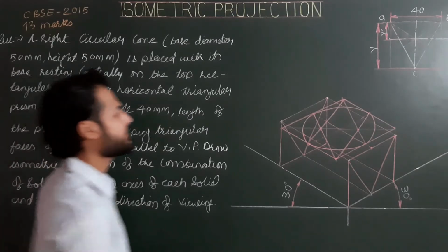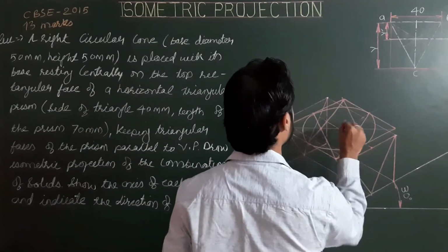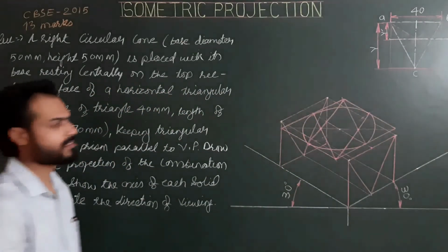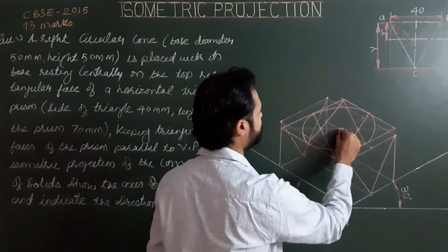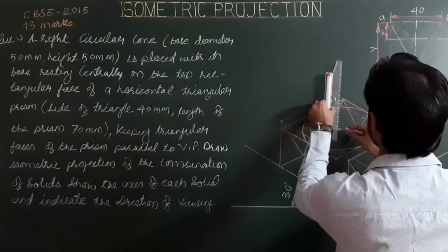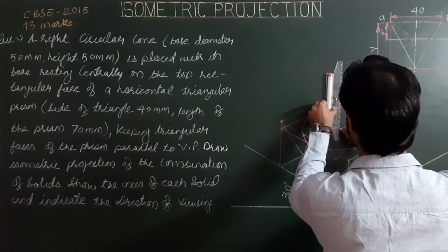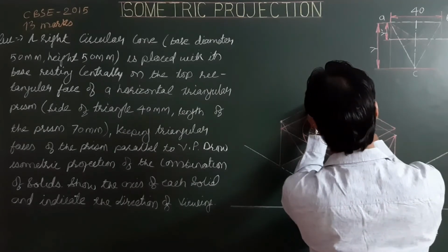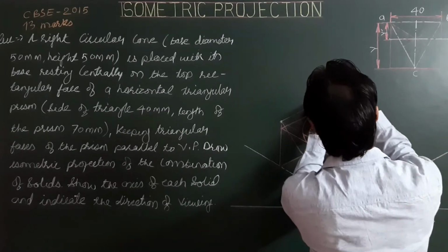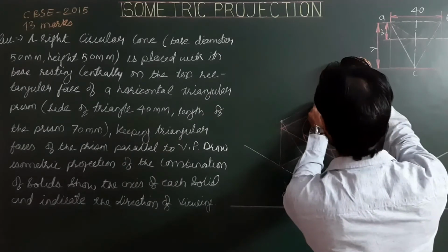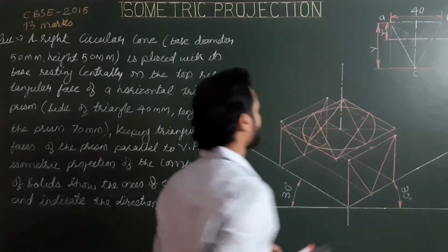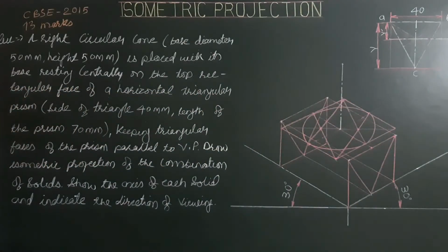From the center of the rectangular face, or center of the circular base, we have to draw a line perpendicular to the third or vertical ISO axis for a length of ISO 50. So this height or length is ISO 50. Now we have the apex point.